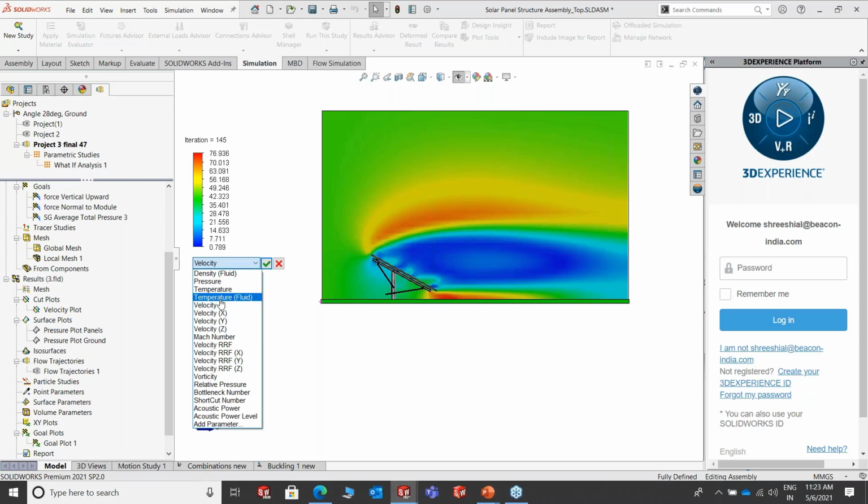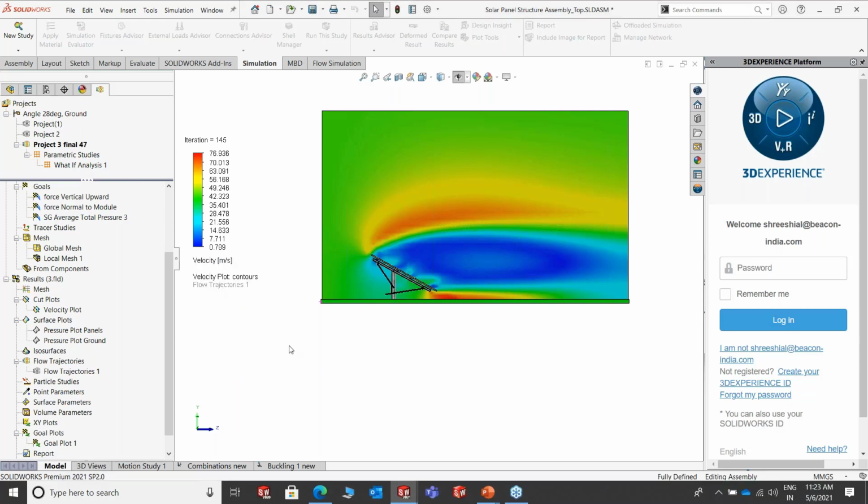Whenever you are doing thermal analysis, especially thermal solar radiation, the temperature distribution is always very important. If you name any parameters related to fluid dynamics or heat transfer problems, we have the post processing functionalities to calculate them, including kinetic energy, turbulence intensity, noise parameters, and many other aspects.